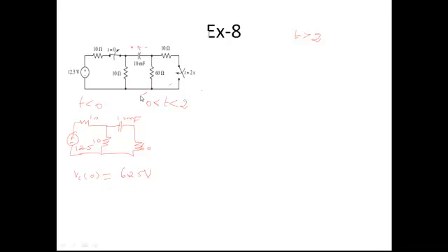Okay, so please understand, you are drawing the first circuit for t lesser than 0. Your circuit is like this. For t between 0 and 2 seconds, that is greater than 0, not equal to 0. At t equal to 0, the switch is open. So after 0, but before it attains 2 seconds, this switch is also open, this switch is also open. Under that case, your circuit is very simple, like this. Correct? Under this case, your circuit is like this: 60 ohms, 10 ohms, 10 millifarad.